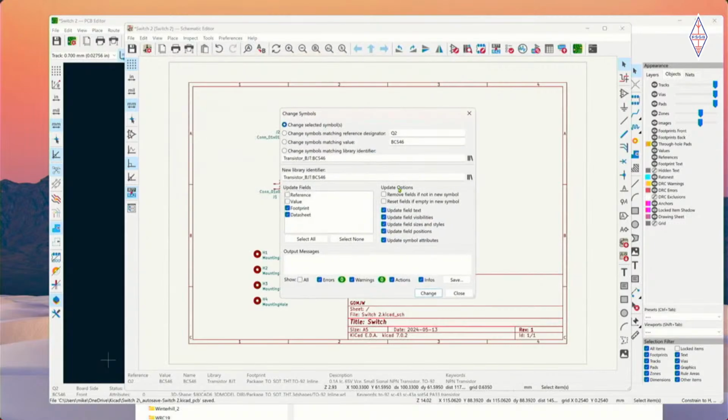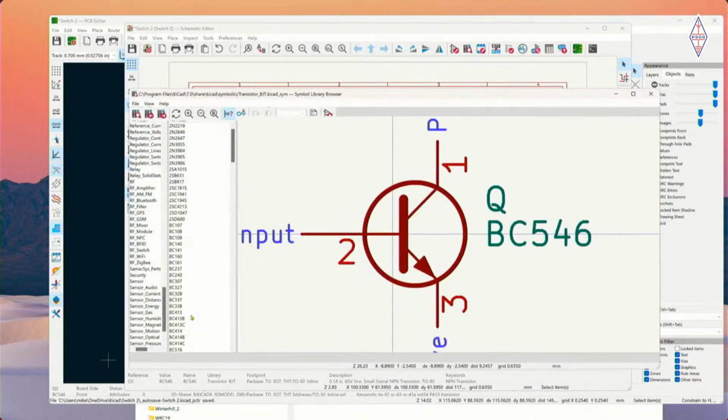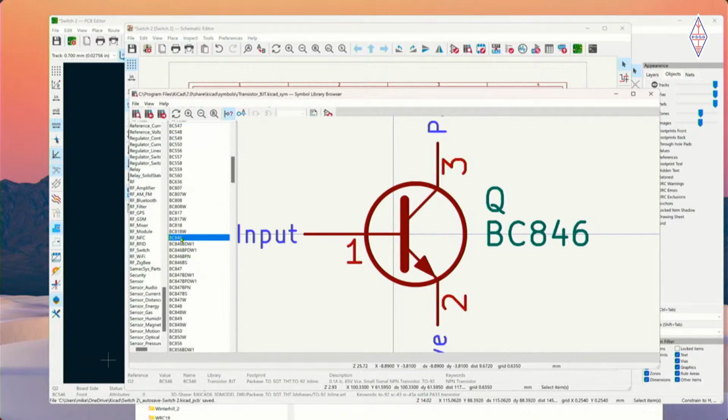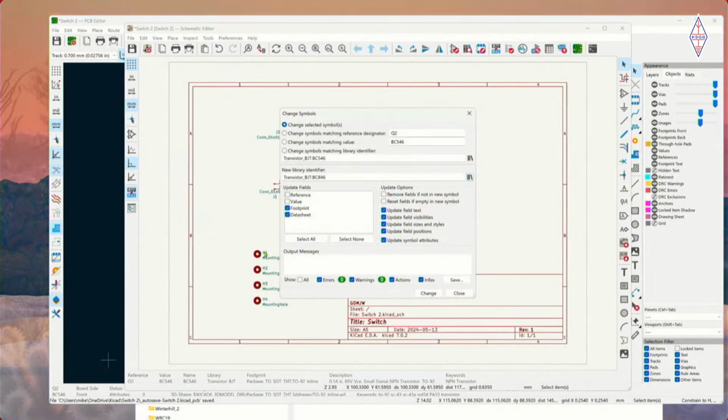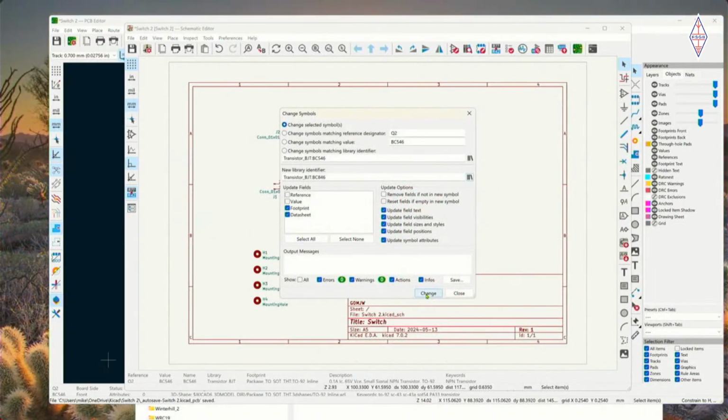So there are no wires that go through holes. That's, as the name suggests, surface mount. And what Mike's going to show us now, it looks like he's going to change one of the components to being surface mount. So I'm just going to change this transistor from a BC546 to what would be BC846, which I think is the surface mount equivalent of that.